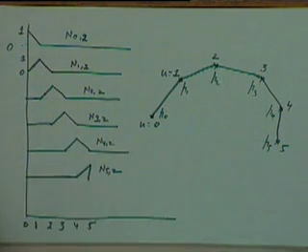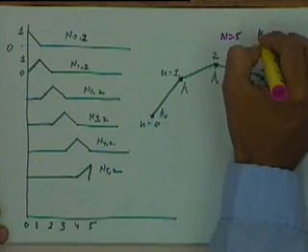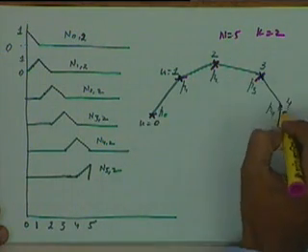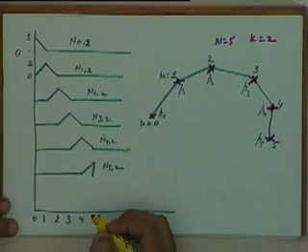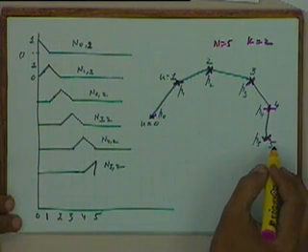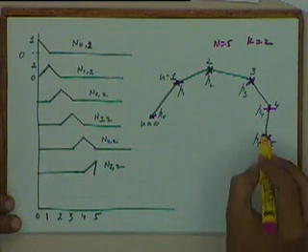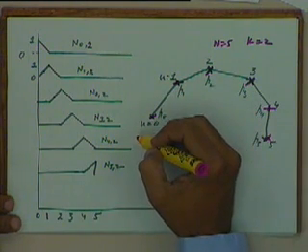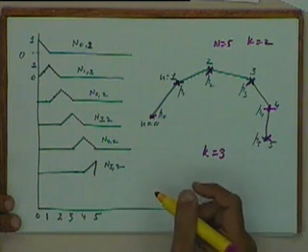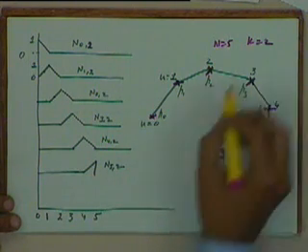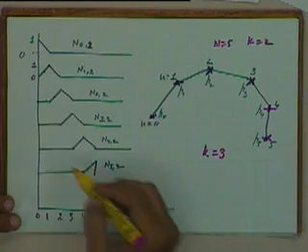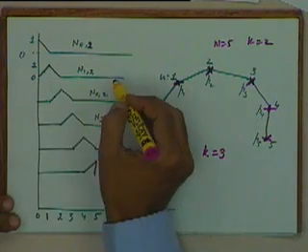Okay. Just to compare, this is the case when n is equal to 5 and k is equal to 2. When k was equal to 1, I had a set of points here like this. Okay, so when k is equal to 2, my curve is continuous, but it has only C0 continuity. Okay, for k equal to 1, the curve was discontinuous. Now when we take k equal to 3, we will get a quadratic curve or second degree curve. Okay, for k equal to 2, I have a linear relationship. All my shape functions are linear functions, linear functions which are defined in a certain range. Beyond that range, the function is 0.